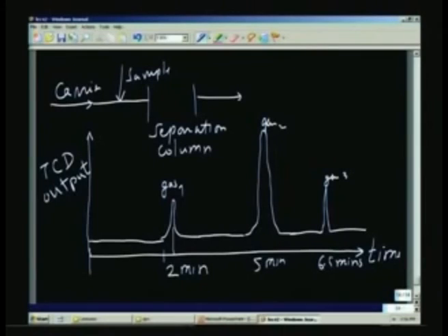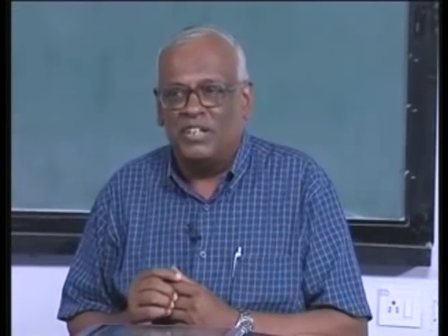If you just look at the peaks, all you know is that these gases are present. If you want to quantify this, then the thermal conductivity of the gas must be known, and how it affects the TCD output must be known, so that we can calibrate with different mixtures. These mixtures are ready made and available from manufacturers, so that you can use them for calibration.